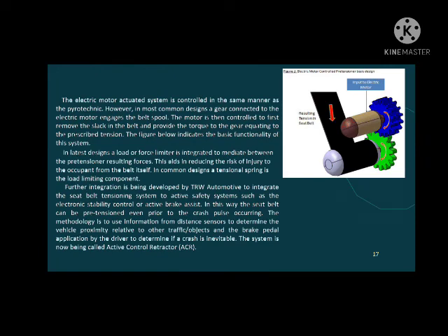An explosive charge is used and causes the gas generator to produce gas. This volume of gas produces a pressure which acts on a mechanical linkage to pull the seat belt. This pre-tensioner is usually located in the B pillar.